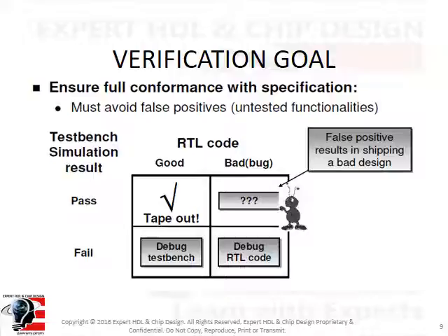During the process of verification, bugs can be in the design or in the test environment. Hence, it is extremely important that tests are clean and also capture all possibilities to test the design under test, so a design with a false pass is not shipped to a customer. Two main factors of clean and comprehensive testing are to introduce randomization in the test to ensure it captures corner case scenarios, and to have the test plan reviewed by the designer and verification engineer to ensure it covers all functionalities of the design.